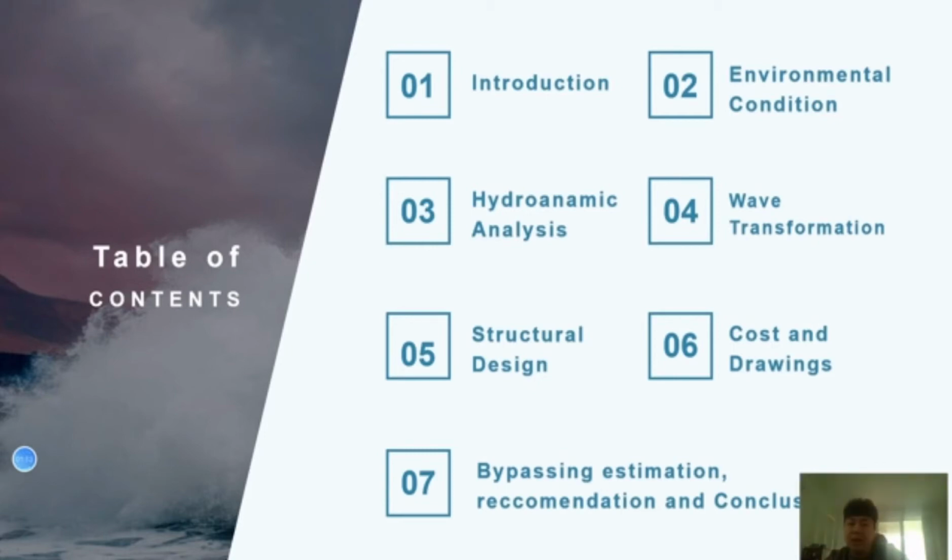After that, hydrodynamic analysis should be considered. In the next part, wave height, wave period, and wave setup can be determined using some formulas and EVA software. Then, the next part is wave transformation. In our report, shoaling, refraction, and breaking should be considered.